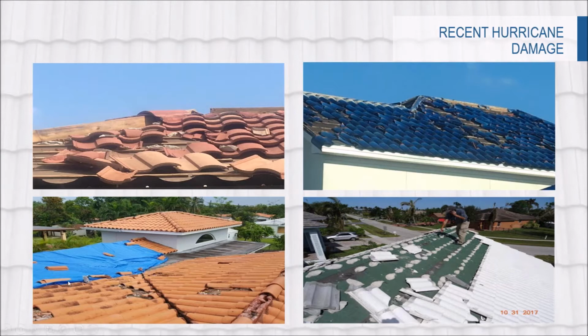that happened. That left photo there, we found out in our studies was a lot of these hip and ridge, these trim tiles that were airborne from these hurricanes, they start to roll and affect a lot of these field tile areas, and that's where you get those sporadic breakages. The good thing about our industry is that they're always evolving and always researching to find better ways to attach concrete and clay roof tiles.